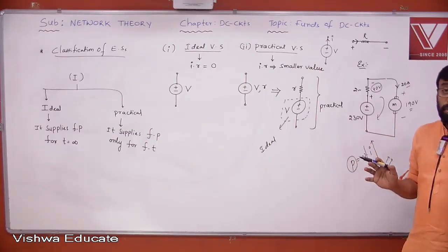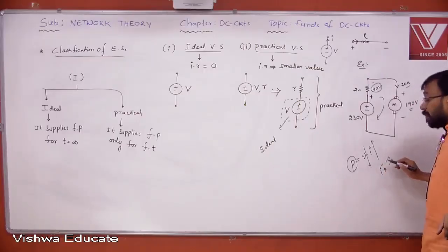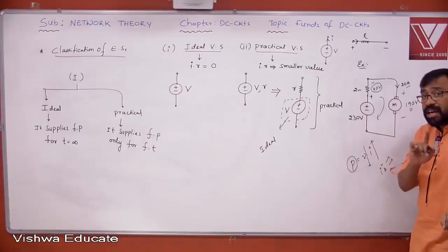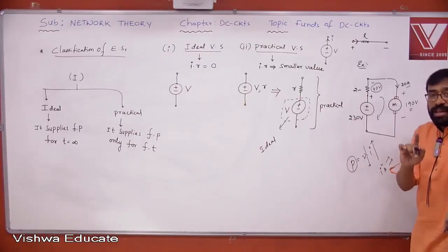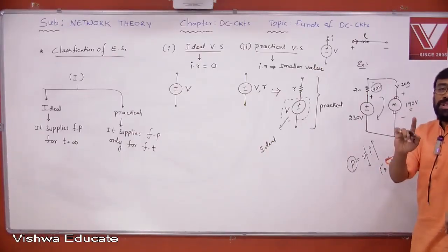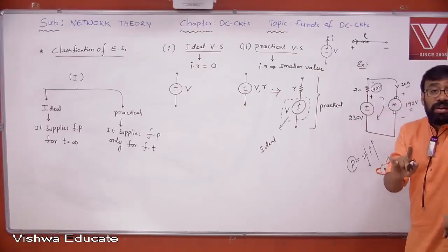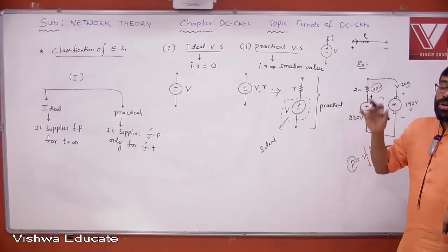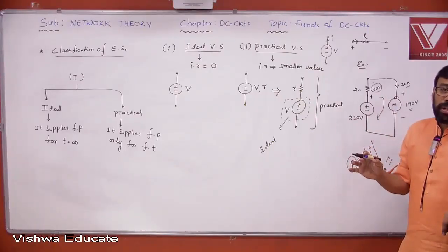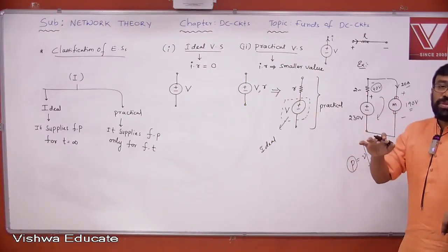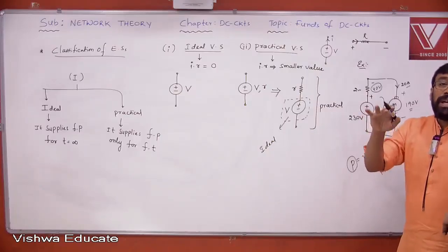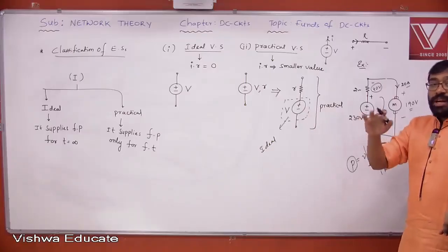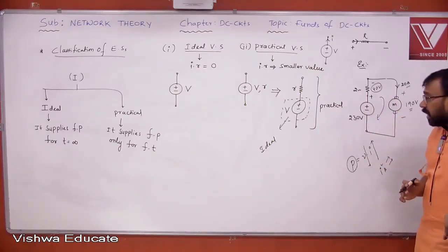Hope you understand. So what do you understand from this? High current may lead to thermal breakdown. Yes or no, all of you? High current may lead to thermal breakdown. That is why during summer holidays, most of the time the windings are gone because of thermal breakdown, and that is because of the load that we operate. A heavy amount of load will be operated. So there is a huge demand during the summer holidays, and the entire power system is under stress, completely fully loaded or beyond the rated load. Mostly it is overloaded. Okay, so this is how it happens.